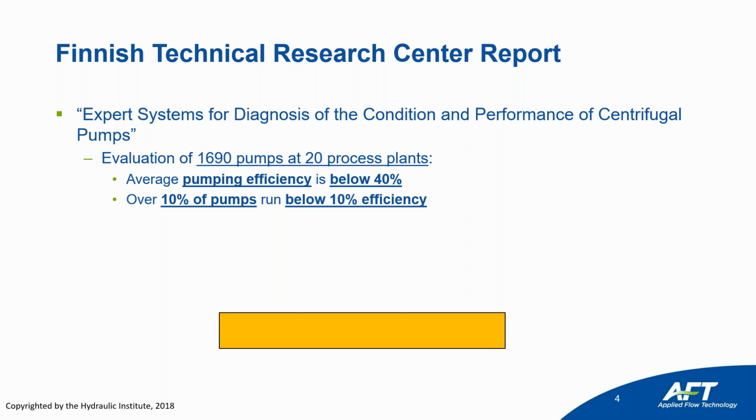Now, think about the outcomes of this. It's not just lots of wasted energy that they're losing. Think about where the pumps are operating on their curves, where they are very far away from their best efficiency points. So it's not just causing wasted energy, they're also going to be having to deal with constant pump repairs and product losses and things going wrong in the plant. And so, in order to ensure safe and clean operation, it is crucial for those pumps to be operating properly.